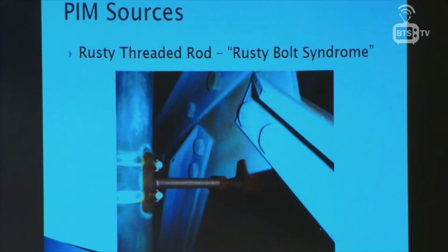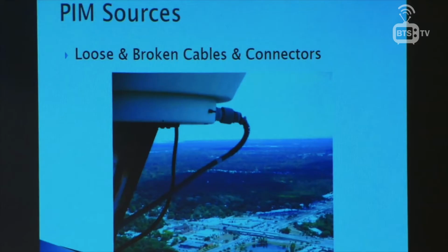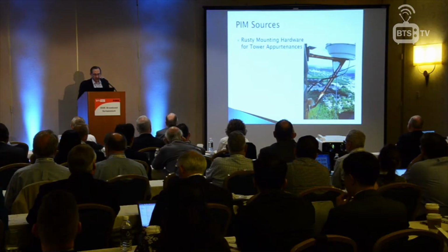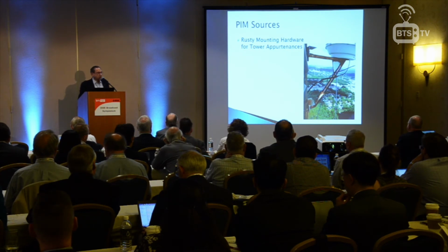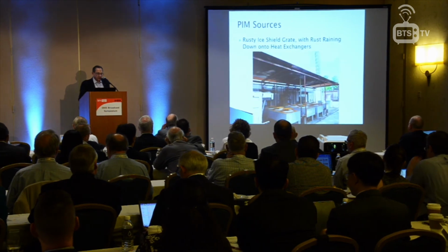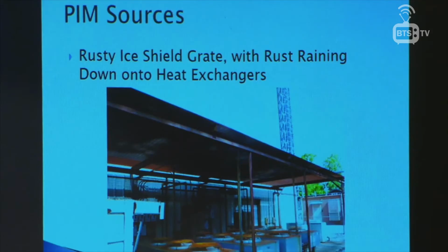Here's another one, the so-called rusty bolt syndrome. Here's a connector that's not properly attached to its cable anymore and is loose on the socket. Here's an example of an appurtenance on a tower that's holding some equipment up that's all rusty. All of these are potential PIM generators. And in fact, here's one more. I'd never seen this one before.